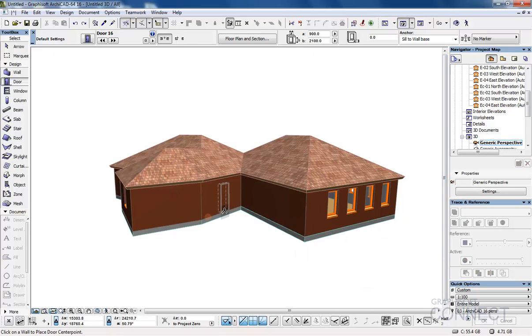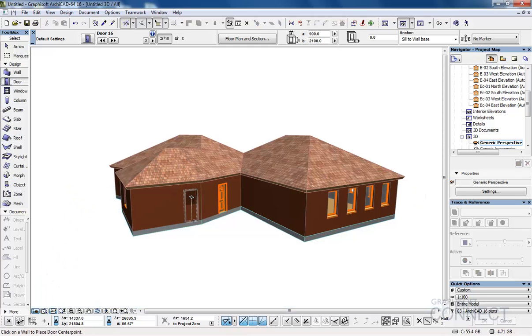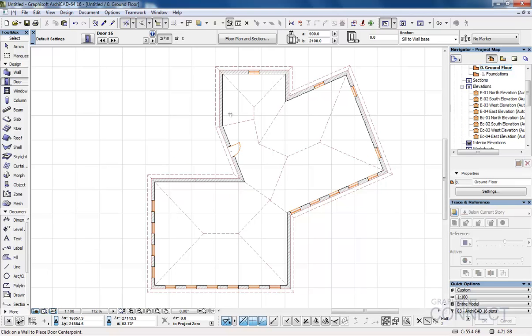All I do is put the mouse on this edge. You'll see there's a marker appears. I can click and that positions the opening, and then what I can do is use the mouse to orientate and choose what side the door opens to. So as I move inside and outside, the marker actually indicates the position of the open leaf of the door when it's in 2D. So if I open it inside to the left, click the mouse, it places the door. And if I drop back to 2D, you can see the plan's updated and we can see the door in its position here.